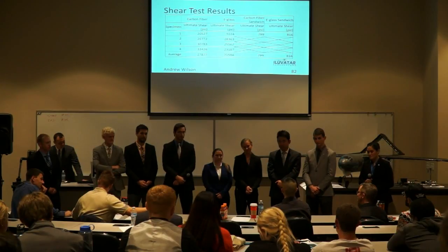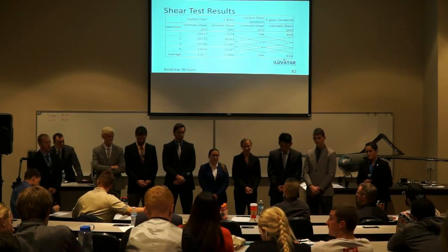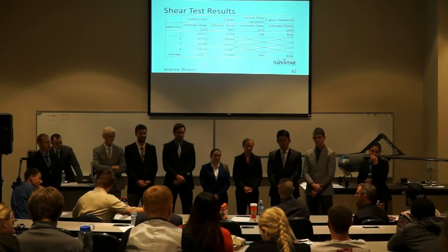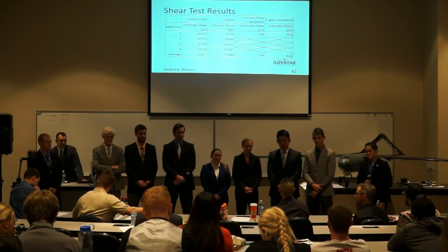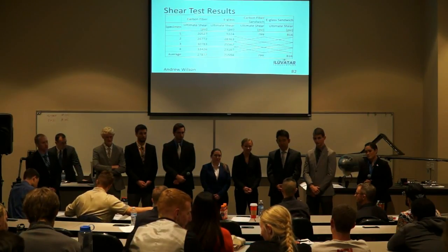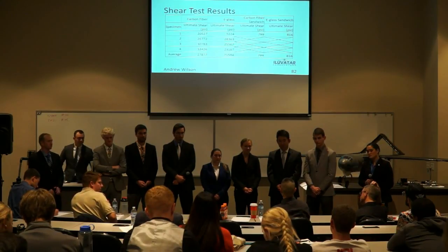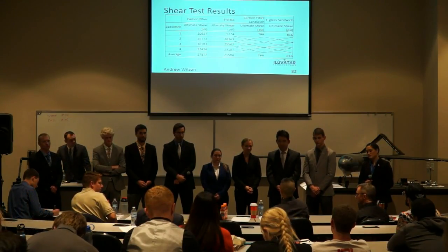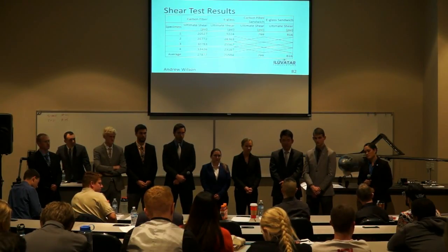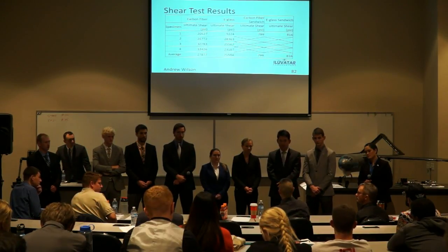Okay, so something just to keep in mind is when you guys start really sizing things up, Dr. Ashworth has this nice nomenclature of does that look right, or does that seem right? So let's take a step back and say 3/1000ths of an inch. On paper, that's what it says, but realistically, this is practical, this is real. When they start looking around the rest of the industry, there's nothing that we can fab, even from composites, that's 3/1000ths of an inch, especially when your starting point is 5/1000ths of an inch dry.